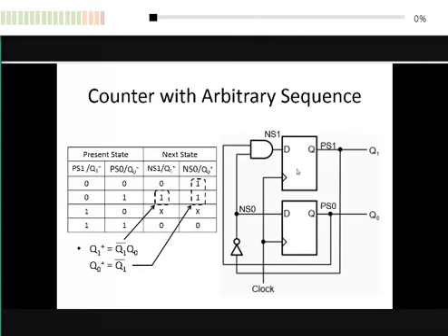All right. Then from the state diagram, we build the state table. And you can see here immediately, we identify the present state which is not used. So the unused present state is marked by don't care. Then after that we fill in the rest of the next state, and then we find the minimized equation.